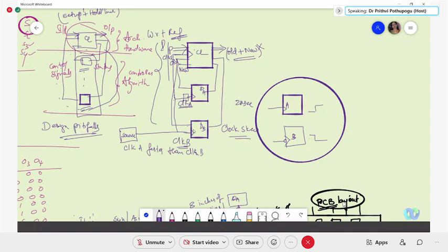That is one remedy. And don't introduce D flip-flops or delay elements in the path of the fast lines. That is another one. The only remedy we suggest for clock skew is running a centralized source having equal distance to all the segments, meaning equal wiring. There is only one remedy.